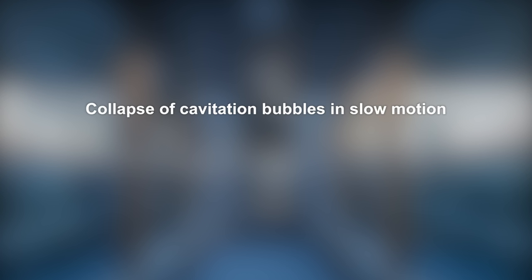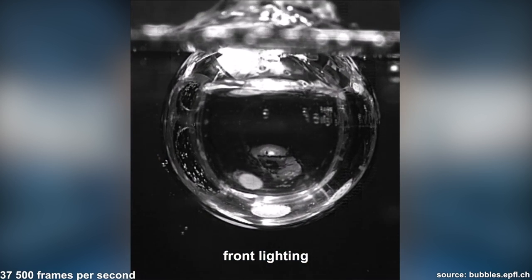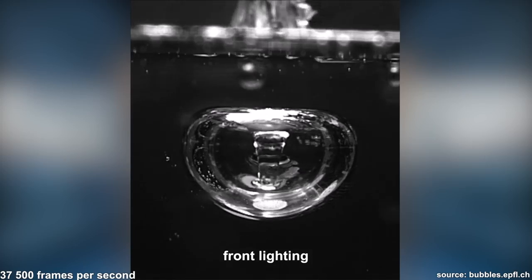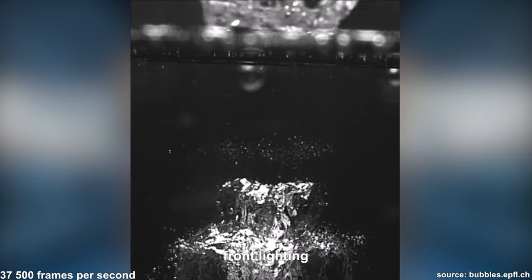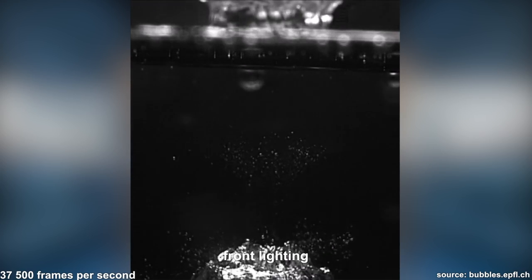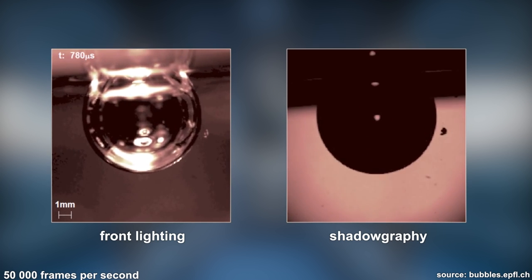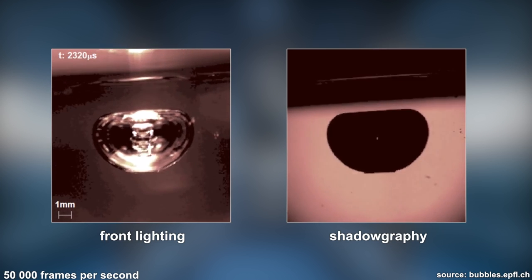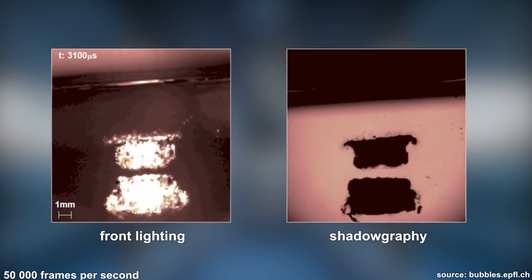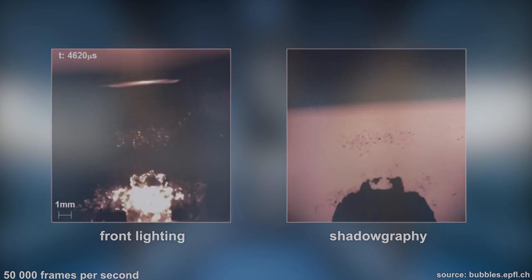But how does it look when cavitation bubbles are formed and collapse in detail? We can see the formation and the collapse of cavitation bubbles with a diameter of approximately 9 mm in slow motion. In real time, this process takes about 4 milliseconds, and it is a spectacular physical event. Because liquid water occupies many thousand times less volume than vapor, the bubble implodes. It first assumes a ring shape. Shock waves and a strong microjet are the result of a collapse.